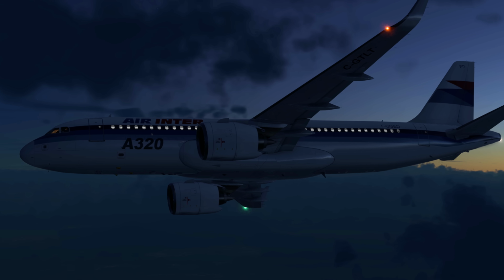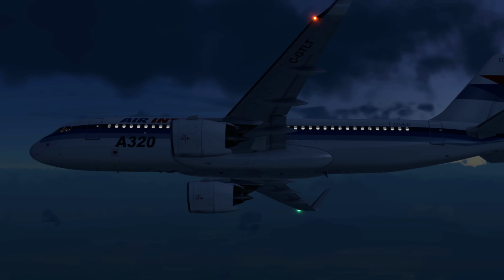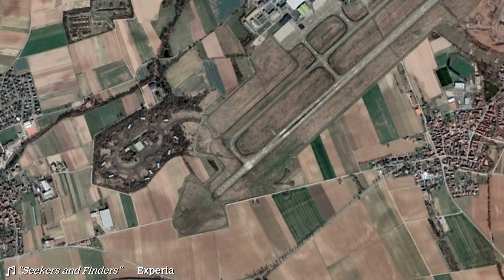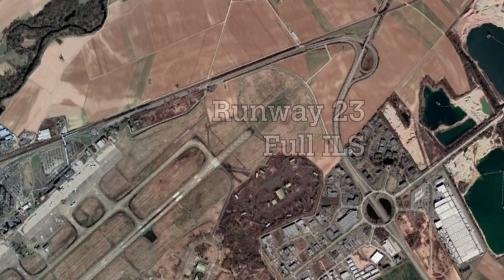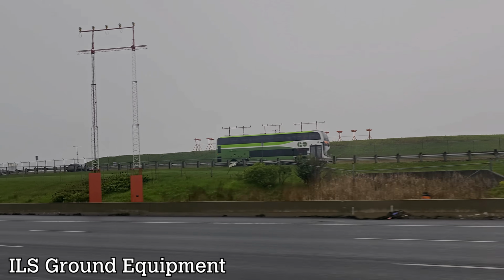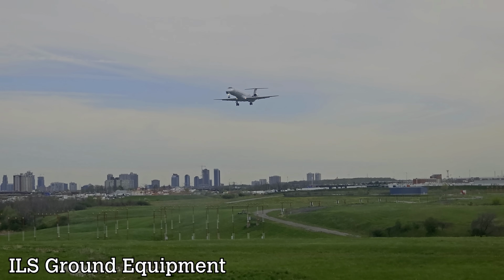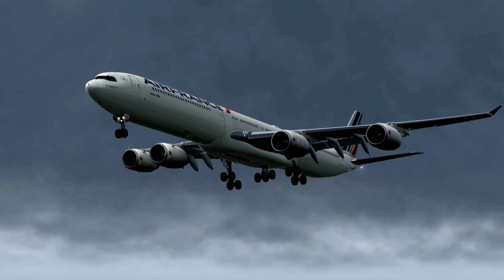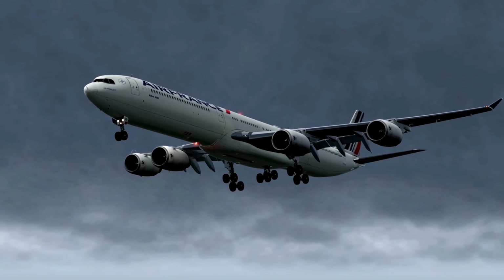As to how the plane ended up here instead of at the runway requires a deeper understanding of the airport. Because of these mountains, there is limited assistance for approaches to runway 05, the approach from the southwest over the mountains. The reciprocal side was complete with full instrument landing system, or ILS for short. The ILS works by broadcasting a radio signal out into the flight path. Pilots can then tune into the same frequency on their radio sets, which can be used to guide the plane laterally and vertically with assistance from the glide slope to the foot of the runway. It's a great tool in limited visibility, for example, and can lower a pilot's workload.